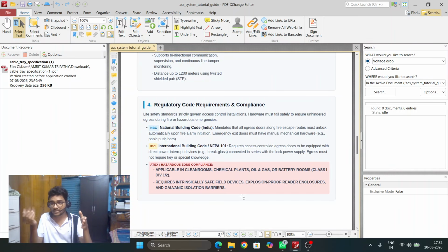But if you check a building which is mostly a semiconductor facility or a modern data center, that building is constructed by following the IBC strictly, which defines that every door in the hazardous areas should have a crash bar inside.